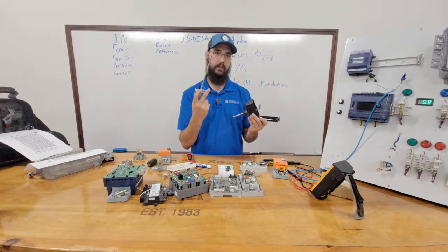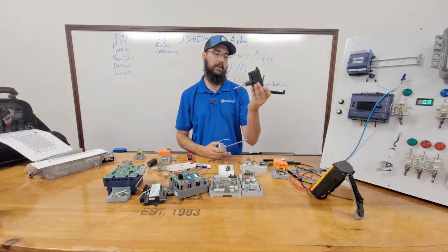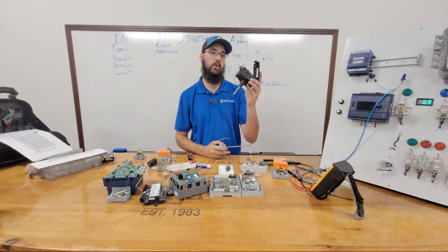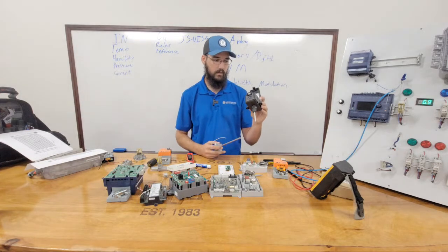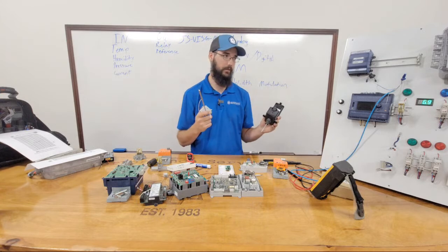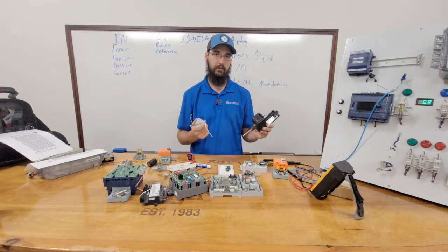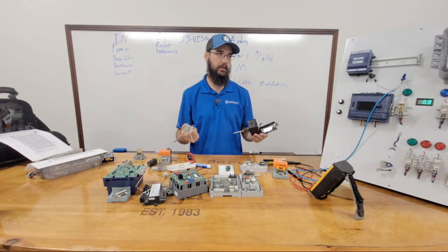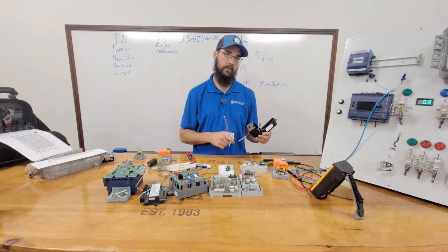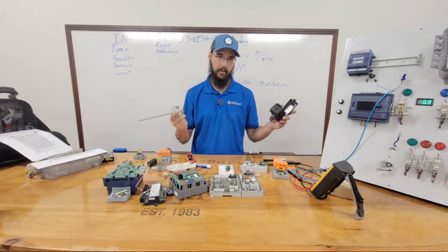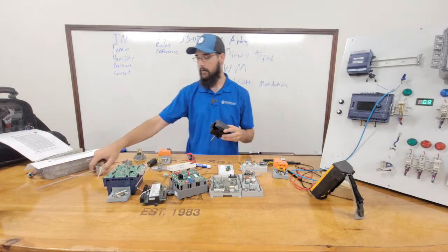This would be something you'd see on ductwork a lot. This one could be duct or water. So yeah. Ultimately, they're thermistors. Just pay attention to their ranges. You troubleshoot them like you troubleshoot a thermistor. You use your calibrated one that you do trust, and compare, and they should either match up or they don't.